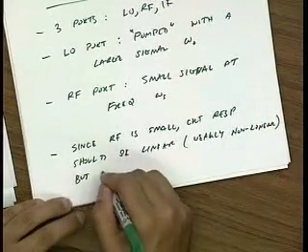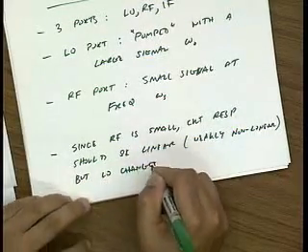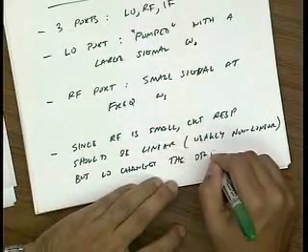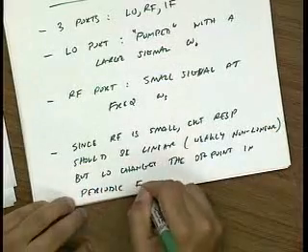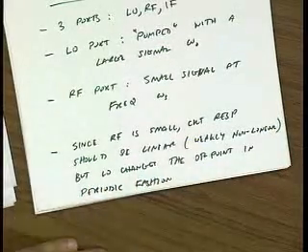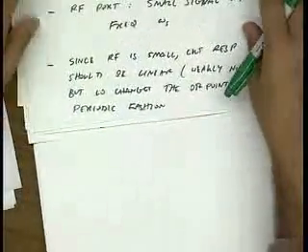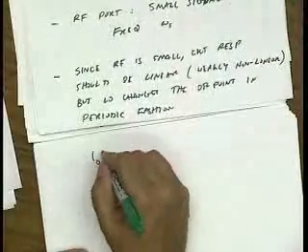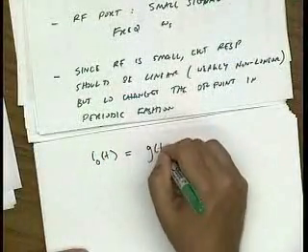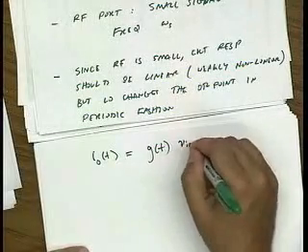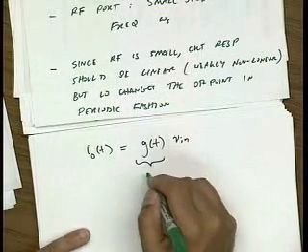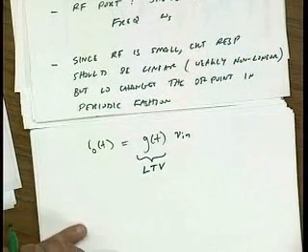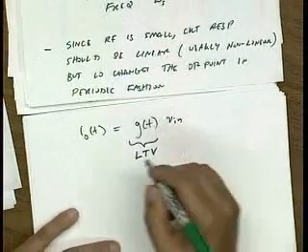But the LO changes the operating point in a periodic fashion. So we can model this as a small signal output current that is a linear function of the input voltage, a linear transconductance, but a linear time-varying transconductance. So this is LTV, or really linear time-varying periodic.